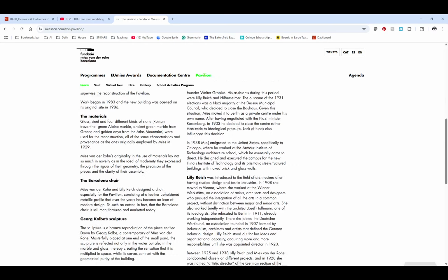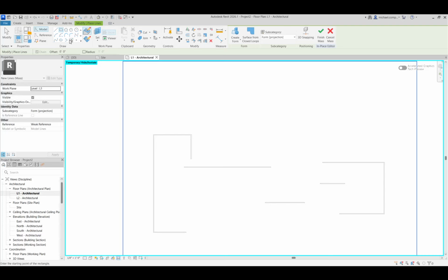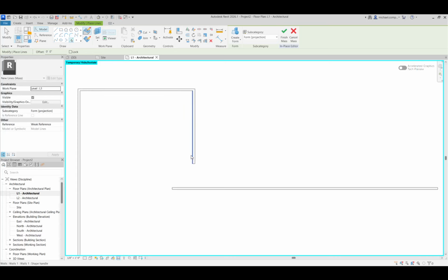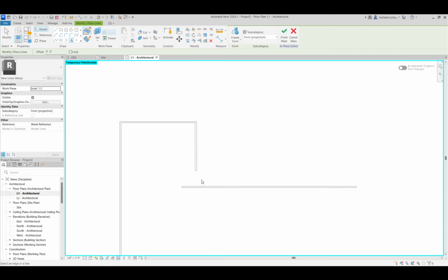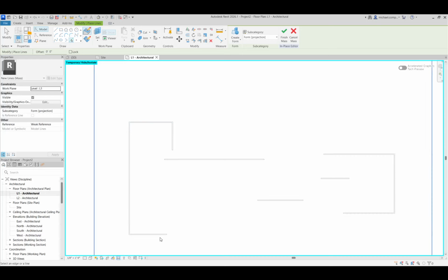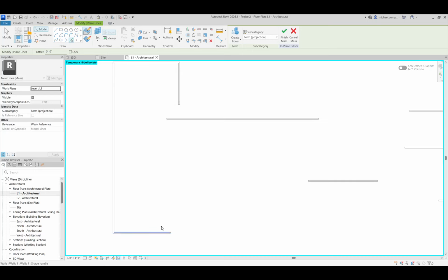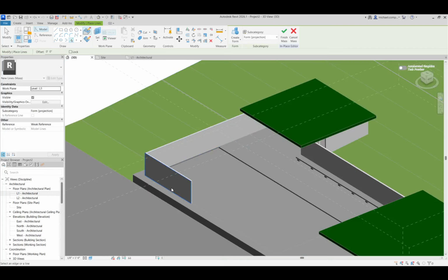So the first thing I'm going to do, just like I would have done before, is start drawing rectangles. But since I already have Revit native line work, I'm going to use the pick tool because that should make my life a lot faster. And I'm going to hover over one edge, hit Tab. Oh, it's not letting me do that actually. I'm not quite sure what it is. Okay, so now it is. Let me Tab, but for some reason it's not selecting all connecting surfaces. Let me try it in 3D. Maybe that makes a difference.